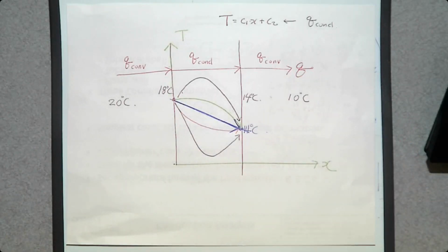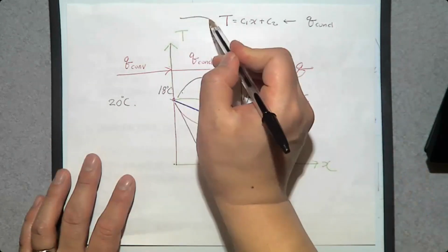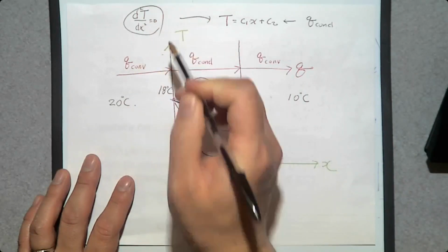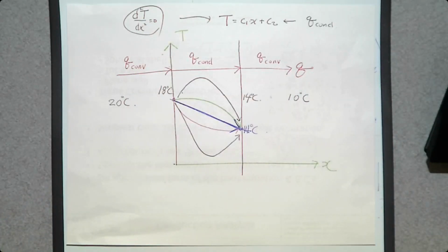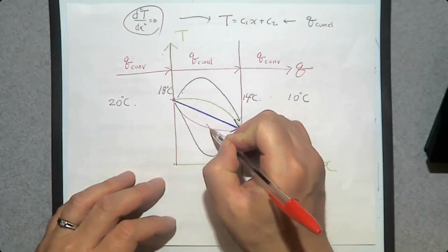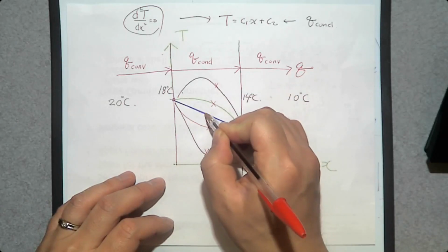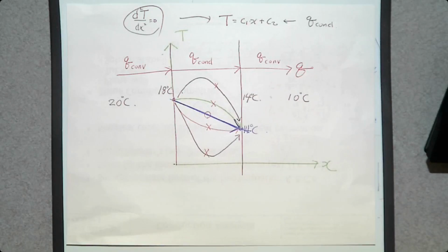So from that heat equation, from this differential equation, d squared T over dx squared should be 0. We now know the temperature distribution within the solid should be first order, flat, straight. Make sense? So the heat transfer temperature distribution shouldn't be this one, this one, this one, or this one. This blue is the temperature distribution.